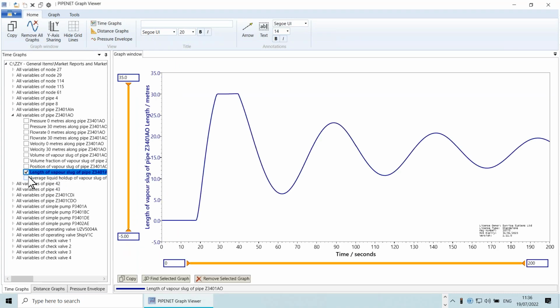Whoa. See, look at this. This is the length of the cavity along the pipe, 30 meters, down to 6.2. So the swing is almost 24 meters. So the cavity length is changing along the pipe by 24 meters. And that is huge. And that keeps oscillating, in fact, 23 and 6, so it's about 17 meters swinging. So it is a big, big problem, the cavity forming and oscillating.